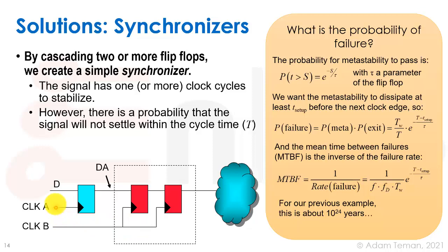What is a path between two clocks? So this flip-flop is clocked by clock A. That means the signal that comes after it is synchronized to clock A. This flip-flop, on the other hand, is clocked by clock B. That means that the capture path is synchronized to clock B. That means we have a path between a flip-flop that's on clock A to a flip-flop that's on clock B, or logic that's on clock A to the capture signal that's on clock B. And that's a big no-no. We can't do that. Well, if we make it by design that it's okay that we're passing things between one clock and another clock, and we can't promise the timing between them, well, that could be okay. The problem is that we have this thing with metastability.